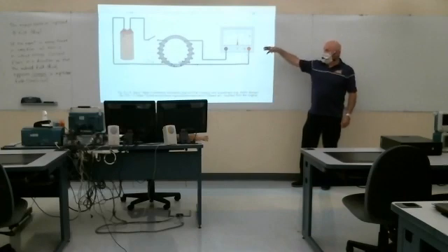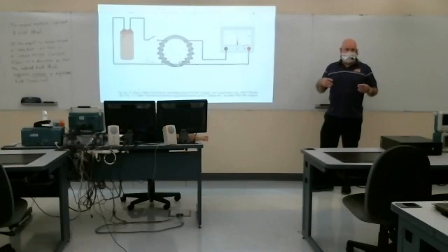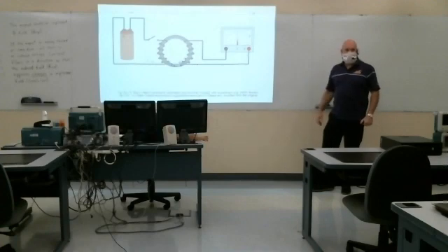Okay. So once the current on the primary side settles down, we wouldn't have an induced B field, we wouldn't have a secondary voltage. Transformers only work when you've got time-varying voltages on your primary. You can't transform a DC voltage. And that's primarily the reason we use AC power. I guess that was the argument between Tesla and Edison. Edison wanted to use DC power, but the problem with DC is you can't transform it.